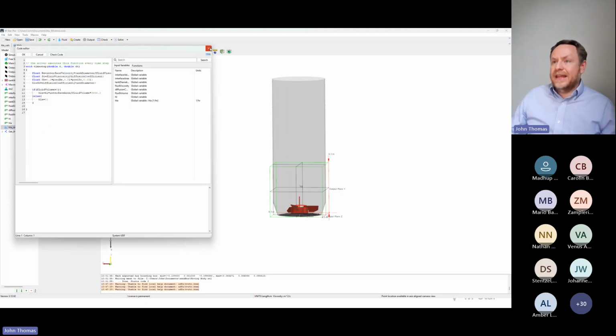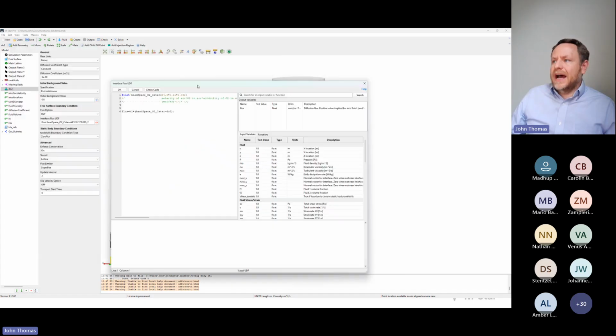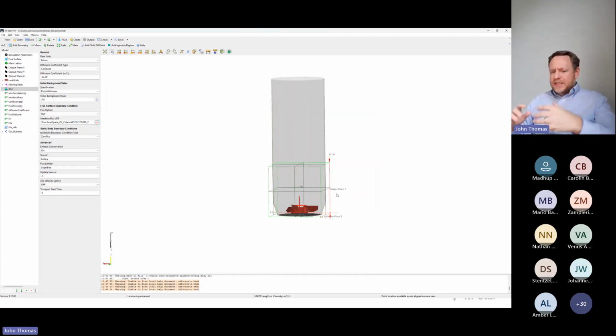It all comes out. And then I also have here inside the DO an interface flux. I've got a headspace concentration, and drum roll please, here it is: HL times headspace concentration minus local DO concentration. There it is. It's just as we had it scripted up on slide 2, where we talked about these mechanisms of transport. So again, I can deconvolve them, see the pathways, see how these all come together.